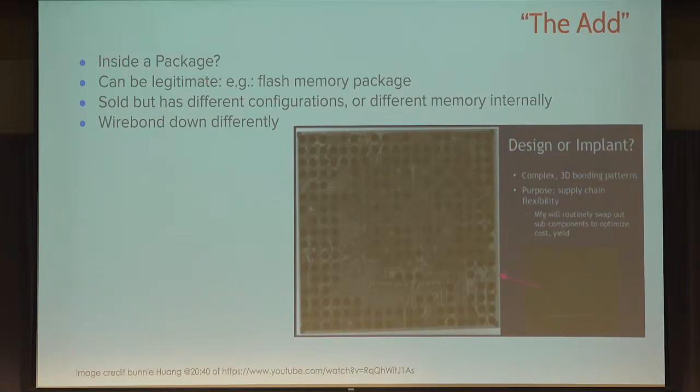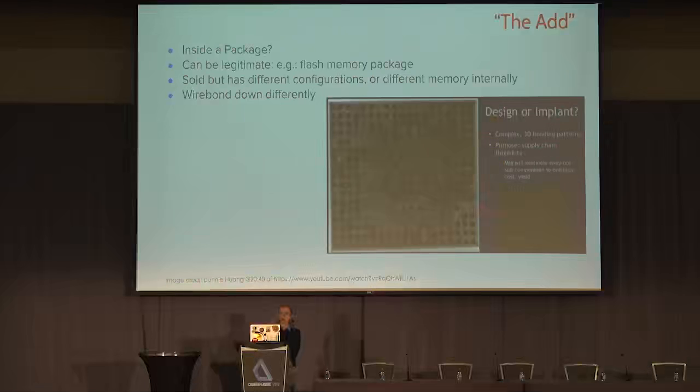There were actually different 3D bonding patterns on this chip. Now, the reason for this was they actually used it for many different types of boards. So they'll swap out different subcomponents that have multiple functionality and then just not solder different vias into the board. And they do that so they can reduce costs, increase the time from start to finish, that sort of thing.